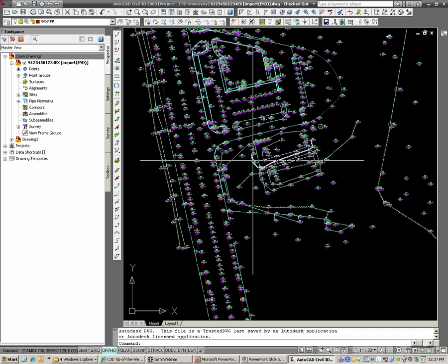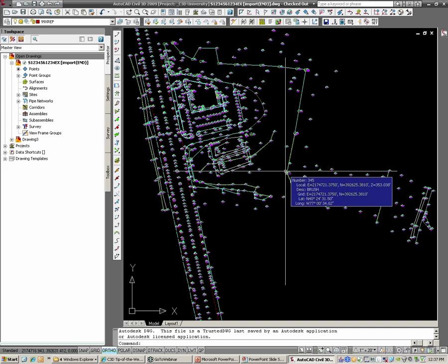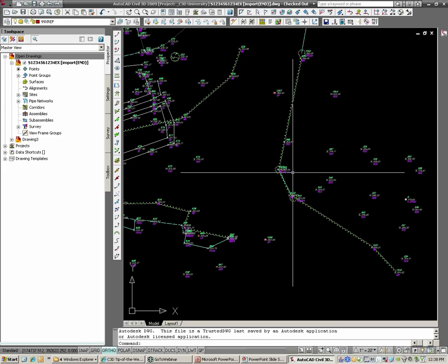And I want to do some things to this. Maybe we went out later and figured out that we assumed some elevation from some information. Maybe we came off a manhole by the authority, something like that. And later in the project date, not too late, hopefully, this whole site needs to be raised up 5 feet. So how do we do that?